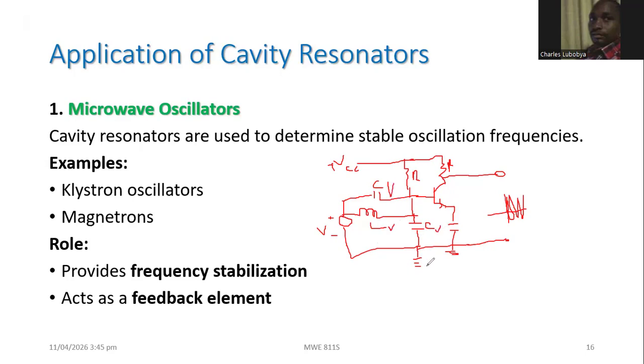So you can actually calculate your resonant frequency, something like 1 over 2 pi multiplied by the square root of the inductor value, this value of an inductor there. And then these capacitors are in series.